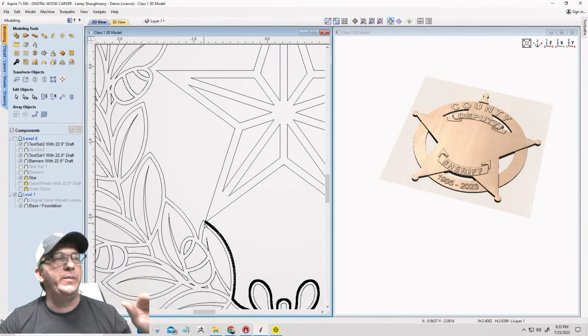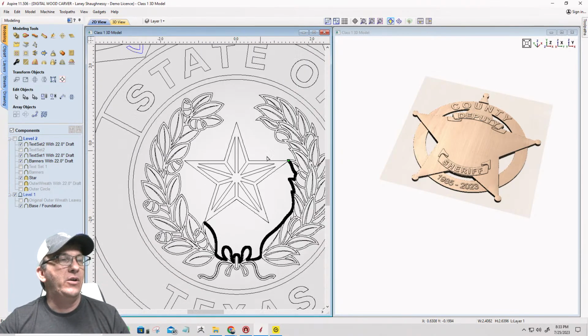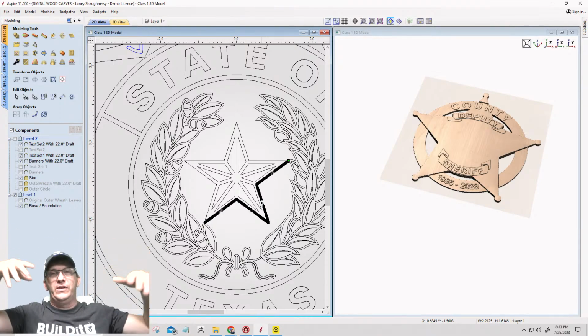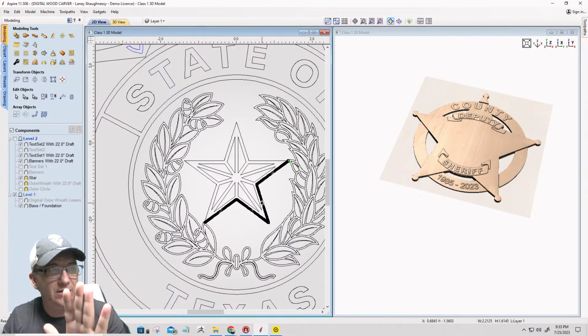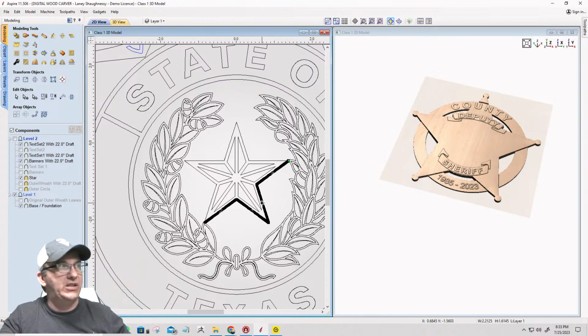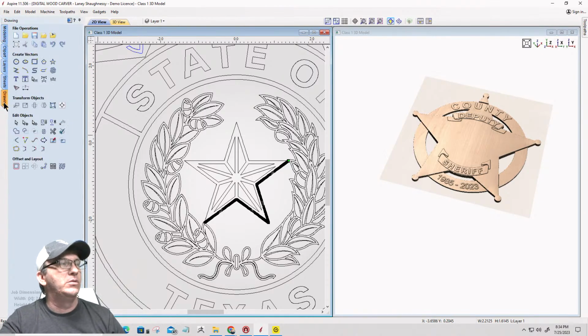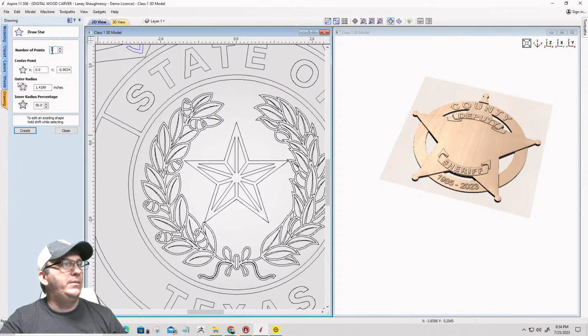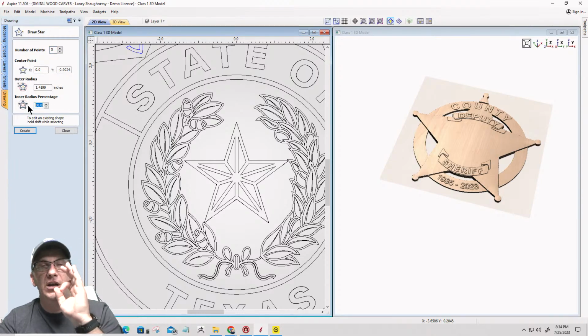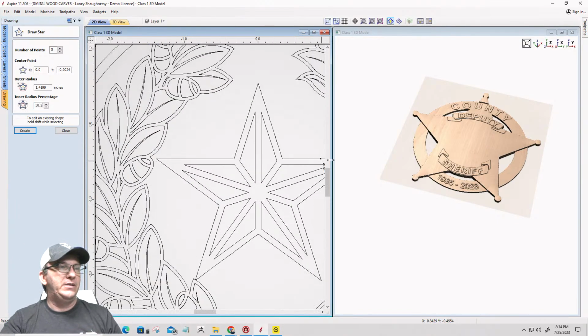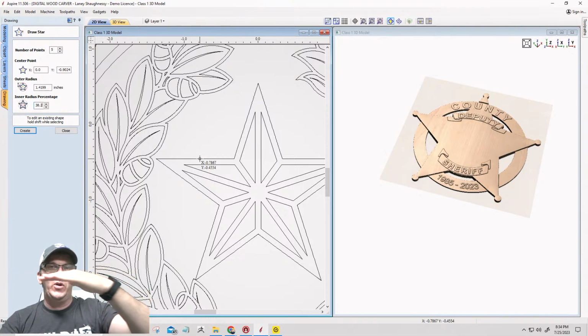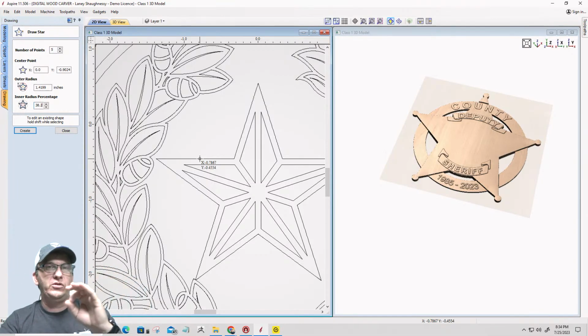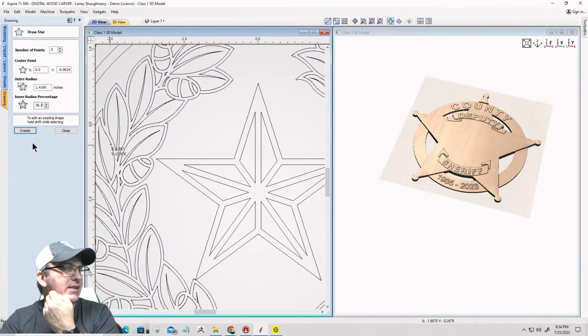What I'm doing is zooming out for a minute to show you that this is a 5-pointed star, and it has all of these nodes, right? If you wanted to redraw that star, you have a star tool in your drawing tools. You can redraw that 5-point star. Make sure that your inner radius is 38.2. That top ledge is flat straight across. So that's a 38.2 inner radius. Always. Your constitutional stars, 38.2 inner radius. That's your magic number.